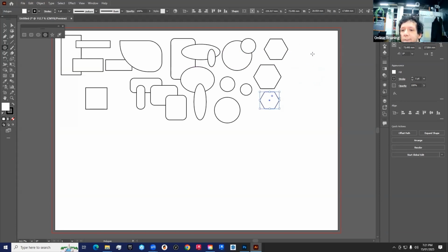Oh, so it's once I've started drawing the shape, so I'm clicking and dragging to draw the shape, and then before I let go of the mouse button. If I've already drawn a shape and I want to change the number of sides it has, on the right hand side of its bounding box, the bounding box being the containing box that allows me to control it, you'll see that there's a little diamond on the right hand side, and as I hover the mouse over that, I get a little plus and minus, and if I drag that diamond up or down, I can change the number of sides, but only up to 11 sides.